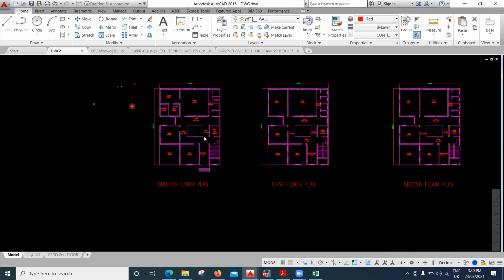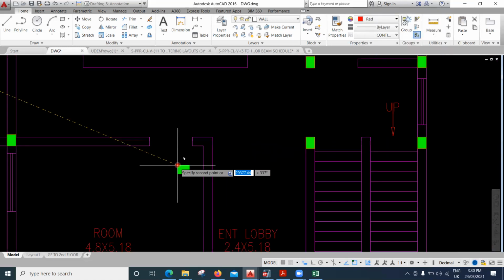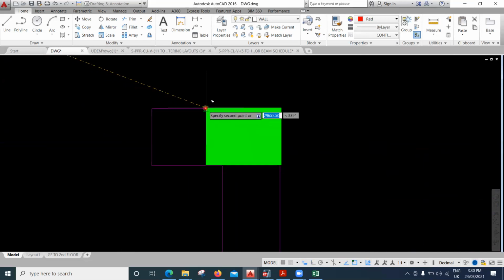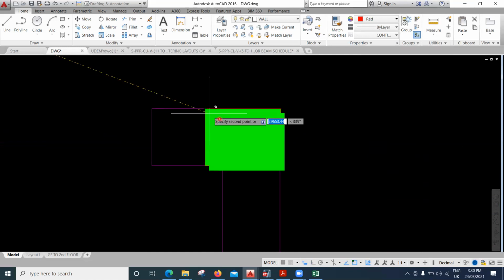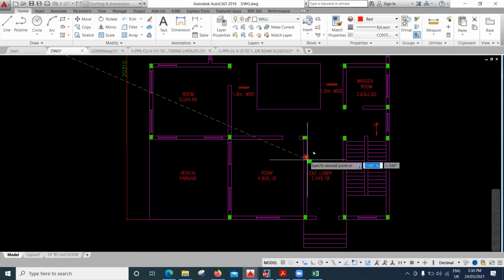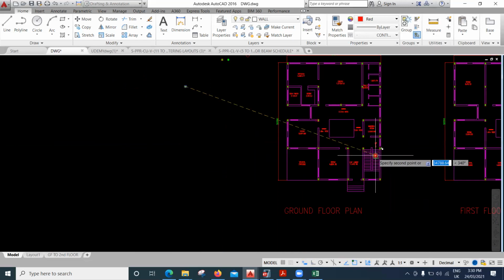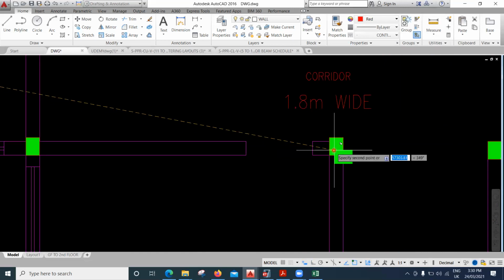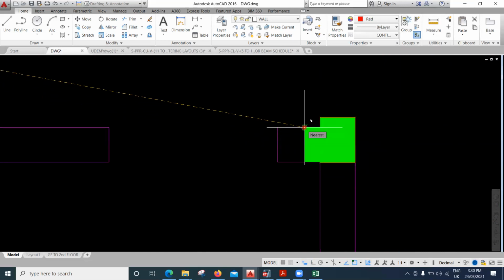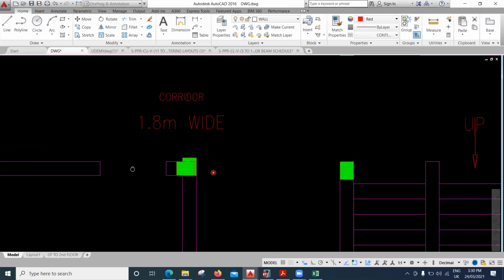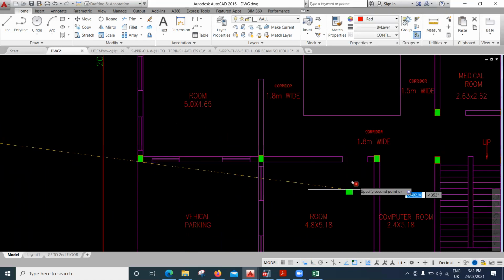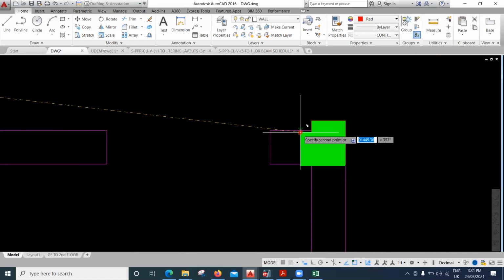What I'm gonna do, I'll take that column and let me place that column here. Now what has happened, that offset what it was creating, it has gone inside the column itself. So I'll change the orientation of the column. Can you see the orientation of the column has been changed? Now there is no offset created. Similarly here also we have to do the same thing. We'll try to delete that column. I'll place this column, no issues. Place the column in this way, and then in the next drawing also try to place the column in this way. Then we'll try to delete that column.